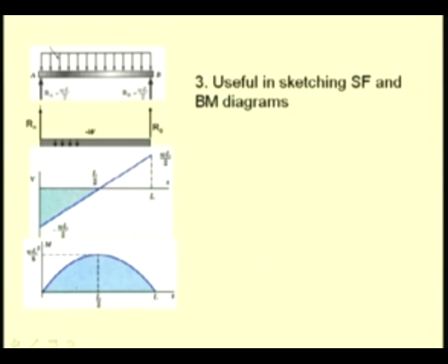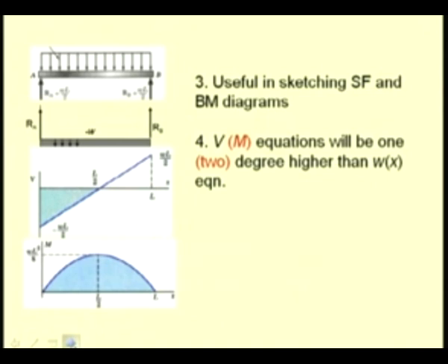And we have found from this example that this can be conveniently used to draw the shear force and bending moment diagrams. And one more interesting thing that we note is the degree of the curve is 1 degree higher between the load curve and the shear curve, and between the load curve and the bending moment curve, the degree is 2 degrees higher.